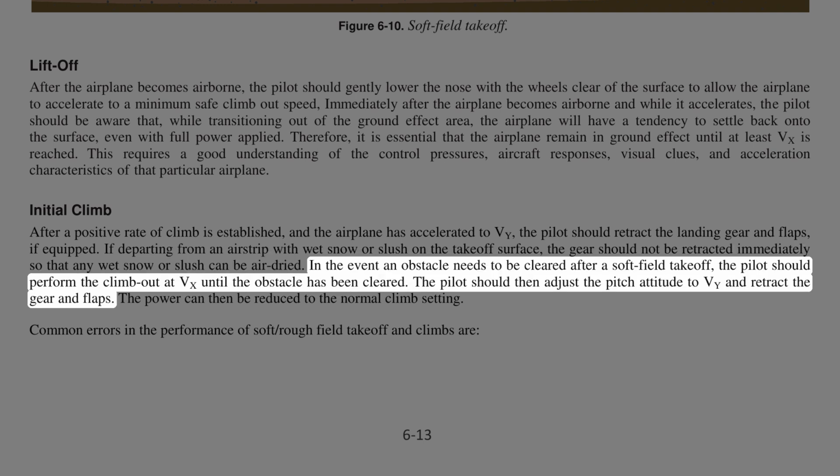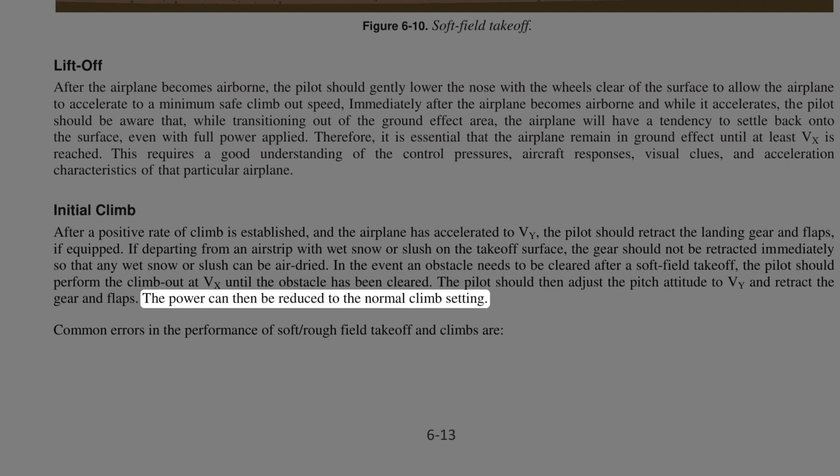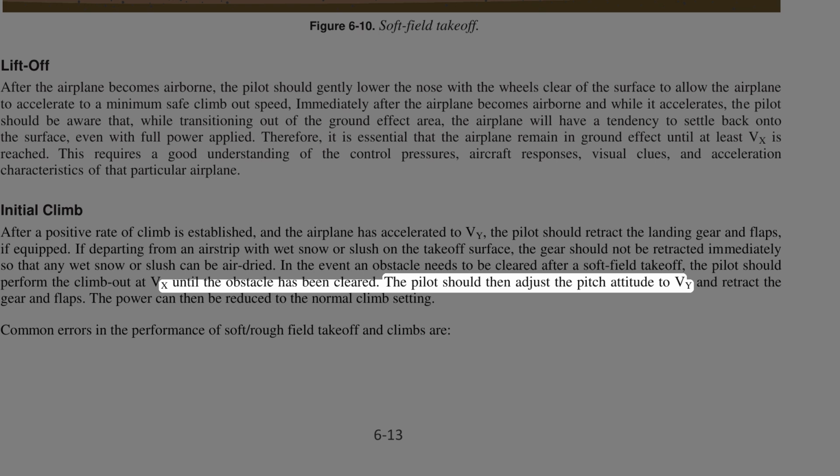In the event an obstacle needs to be cleared after a soft field takeoff, the pilot should perform the climb out at VX and retract the gear and flaps. The power can then be reduced to the normal climb setting. Until the obstacle has been cleared, the pilot should then adjust the pitch attitude to VY.